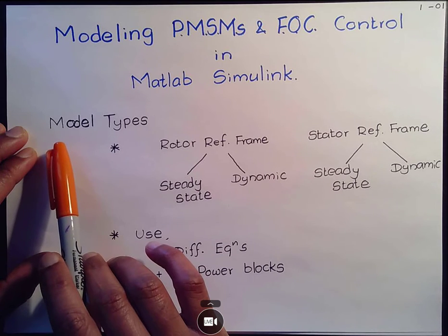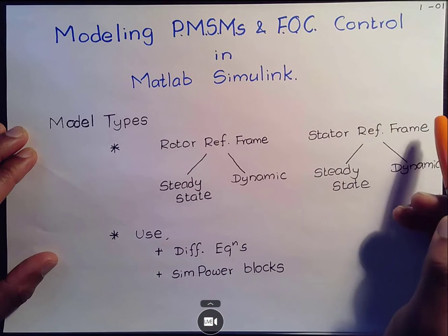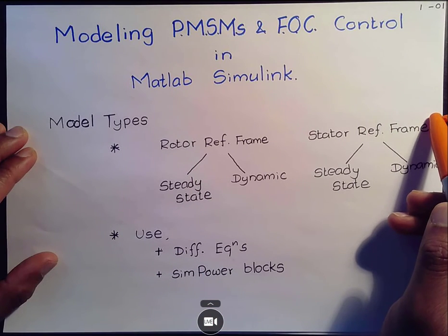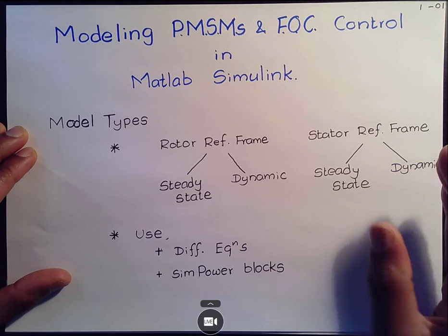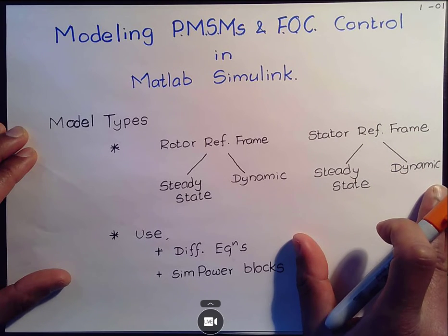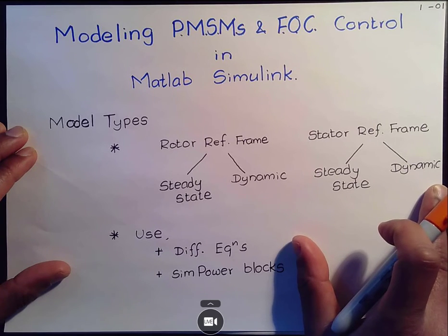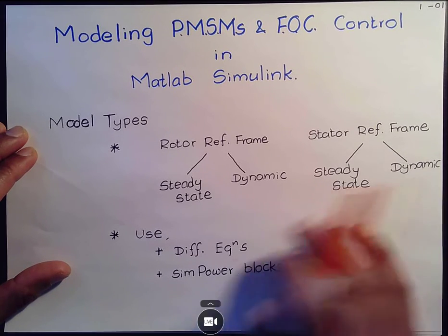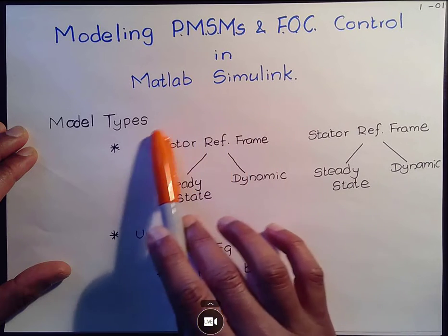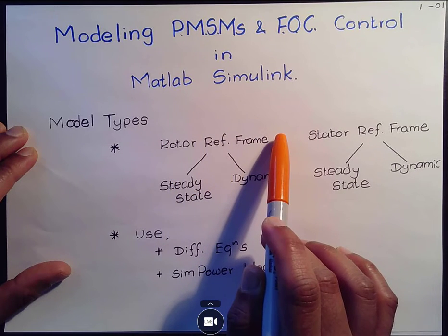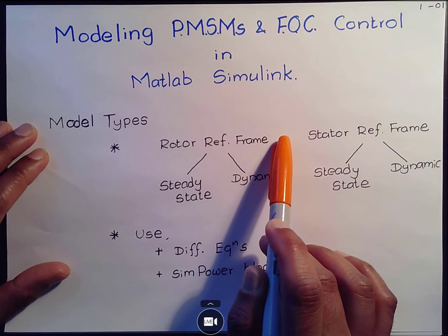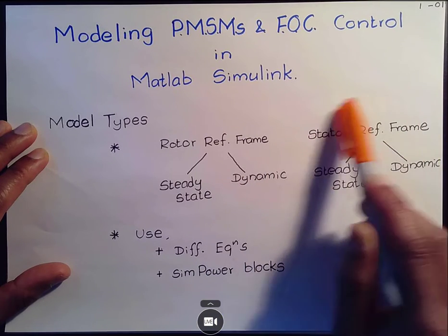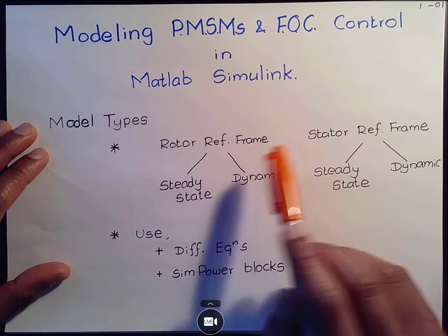Looking at these different models that you come across, basically you are trying to model an electromechanical energy conversion system, which is represented by differential equations in MATLAB. You typically see what's called the rotor reference frame model, and then you'll also see the stator reference frame model.